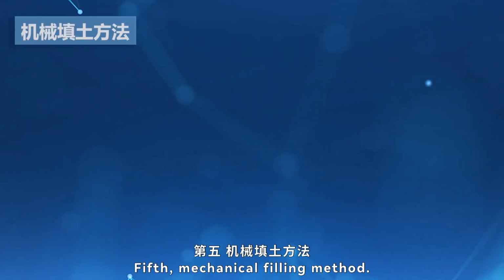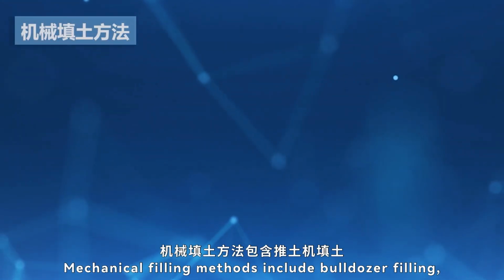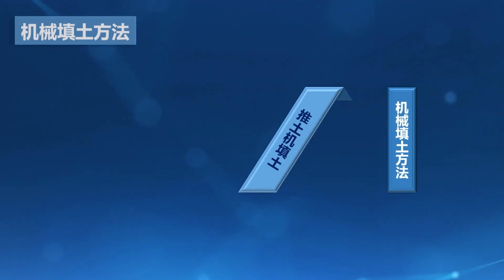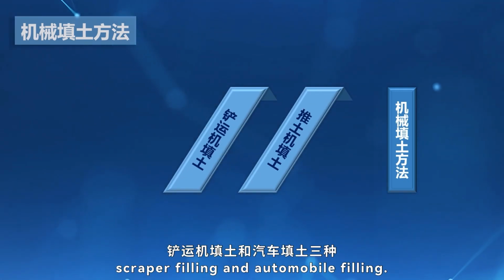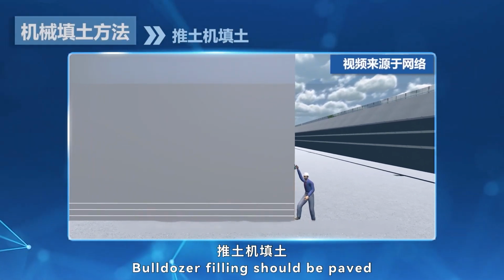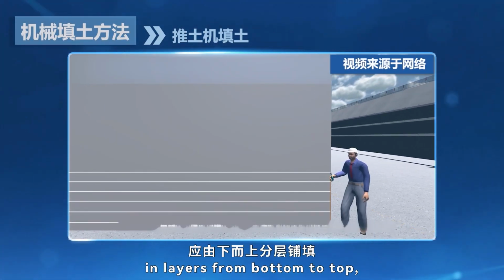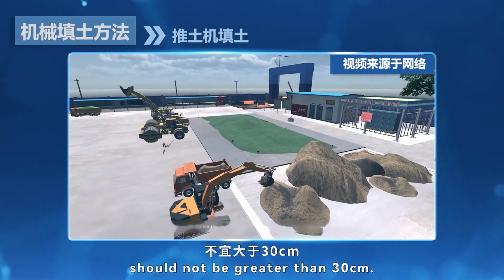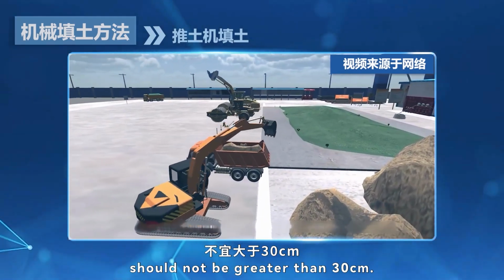Fifth, mechanical filling method. Mechanical filling methods include bulldozer filling, scraper filling, and automobile filling. Bulldozer filling should be paved in layers from bottom to top, and the thickness of each layer should not be greater than 30 centimeters.